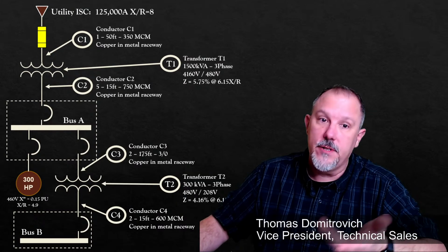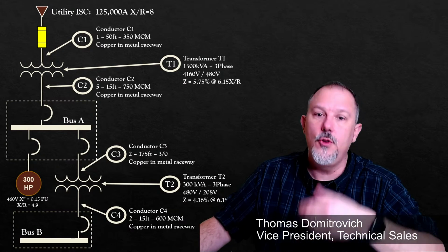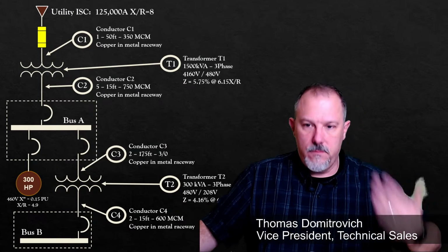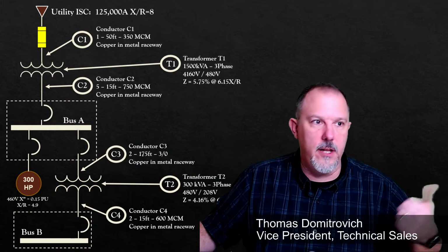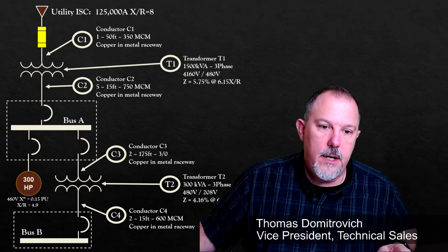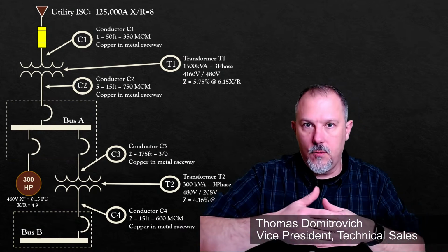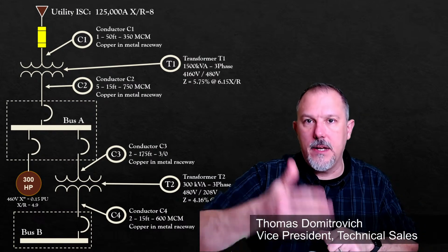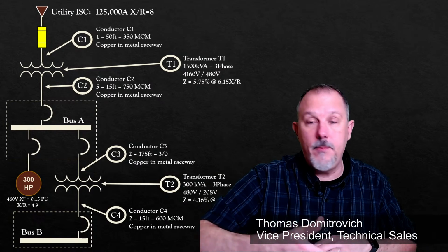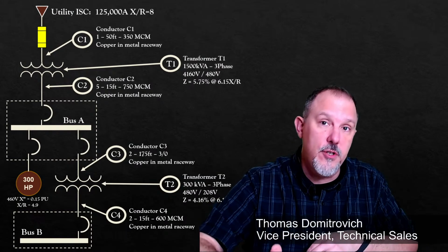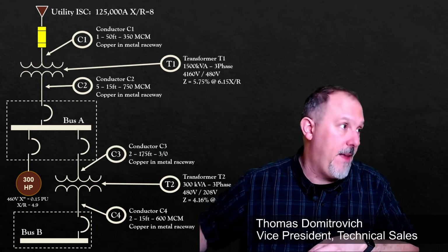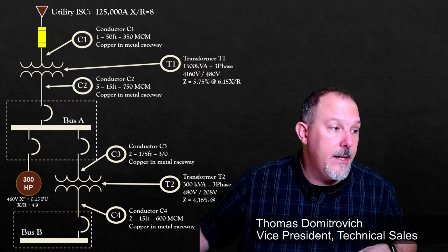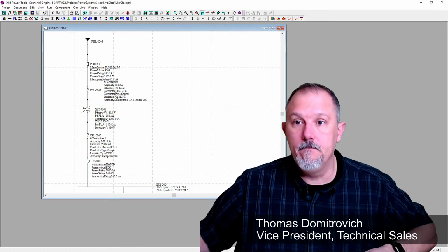It's up to you and your design, but you can avoid the repetitive nature of close it, let it trip, close it, let it trip, close it, and it holds. Think about that instantaneous pickup, think about the transformer inrush, and maybe go up. Instead of doing 1.25, go to the next larger size up from that. That might make your life a little bit more simple.